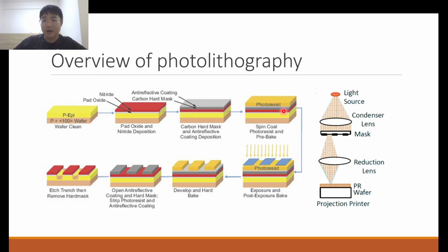Then after that, what we call a photoresist is deposited on the surface of the wafer, following which we expose the photoresist, and this is a step in which a pattern is imprinted onto the photoresist via UV light, followed by a development of the photoresist as well as solidifying the photoresist, and then with the pattern defined on the photoresist layer, we can do whatever processes subsequently to carve this pattern or imprint this pattern onto the wafer substrate itself.